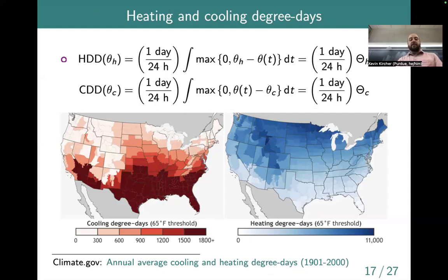It's not too hard to find databases because it's just directly calculated from weather information of the heating degree, what are called heating degree days. So this would be in units of degrees Celsius or degrees Fahrenheit times days rather than times hours, which is what that data thing is that I showed. You can find that for both heating and also for cooling.